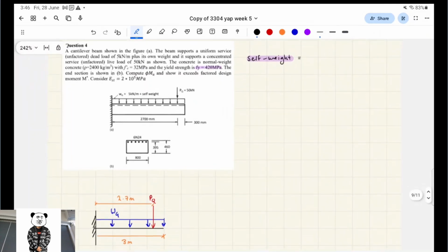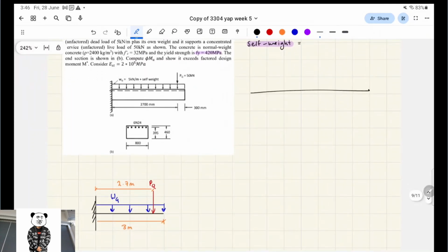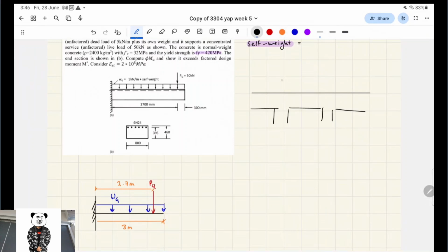Yeah, you're right. Something I mentioned before in my last yap was that in a slab system, the beams that look like that are poured in situ, so they're poured on site, and so the beams and the slabs are poured together, right? So all we're saying with the beam is that, okay, we can consider that this is the area of the beam, but in reality, it's actually a bit stronger because of the rigidity due to the slab assisting it and giving it additional strength.